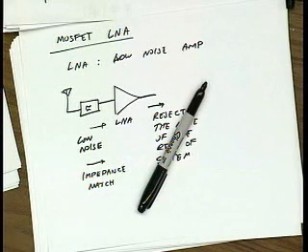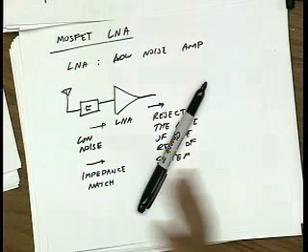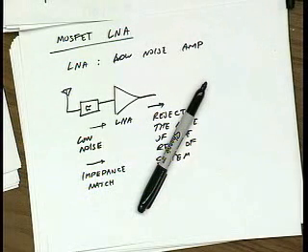Basically they want to say, yeah, this amplifier is matched to 50 ohms. Go ahead and connect it to a transmission line that's 50 ohms. It can be as long as you want. Of course, the longer you make it, the more power you'll lose, but ultimately, regardless of frequency, you're going to get a certain amount of power into your LNA. So having an input match is very convenient. Okay?